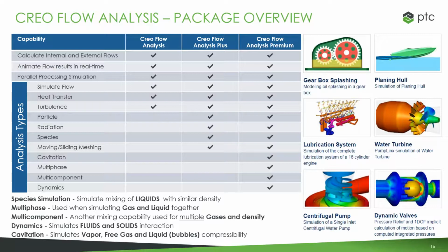If you're designing valves and doing internal stuff, the basic tool works quite well. The advanced tool is necessary if you have any parts that are moving, which is quite unique, actually, the ability to design valves and pumps and things like that. So most users can probably use Analysis Plus and be quite happy with it. If you don't need radiation, you might get away with the basic version. It depends on what you're doing.